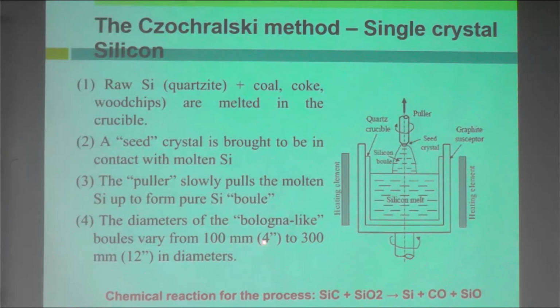So basically, the challenge here, just a little on the process itself, is that getting a bigger diameter silicon is a challenging process, because it will be very heavy. The setup to pull it up requires a lot of work to get this kind of shape with a large diameter. Then you want to control the purity as well. Controlling the purity when you grow silicon is also a difficult process. That's why it's in a controlled environment and it's a very slow process to produce silicon.